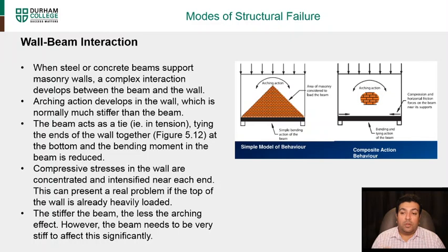That can present a real problem if the top of the wall is already heavily loaded. So the stiffer the beam, the less the arching effect. The beam needs to be very stiff to affect this significantly. So this is another thing we have to take into account when we're designing with openings with beams or lintels. We have to make sure of the loading on top of those beams and lintels, and how it would impact the opening or the bending action.